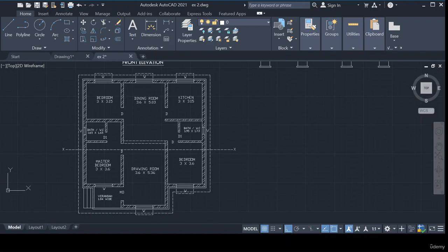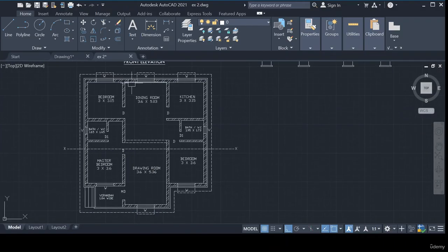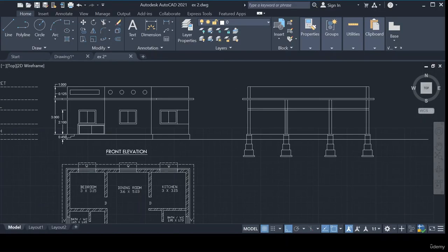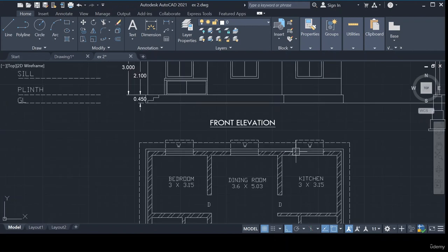If it is considered as an opening, then if you cut this section and we stand and see here, this window will be visible, correct? This window we need to draw here. How to draw that? We can directly project here also, but it is not exactly above that. So just see the distance. What is the distance of the window from the corners? That is 1.05 from the left corner, and from the right corner 1.05.